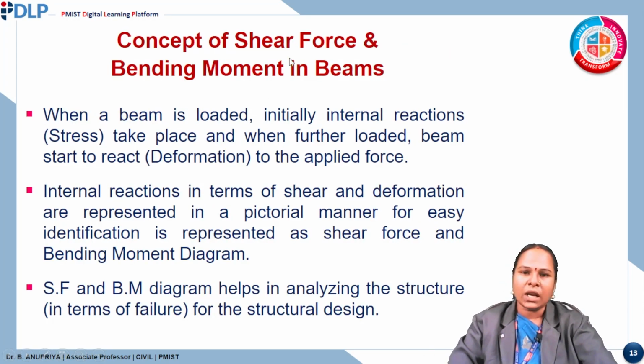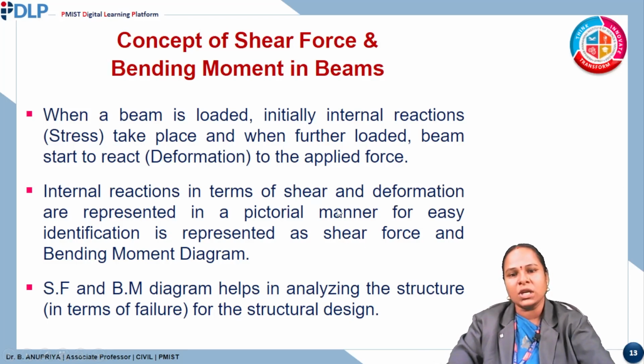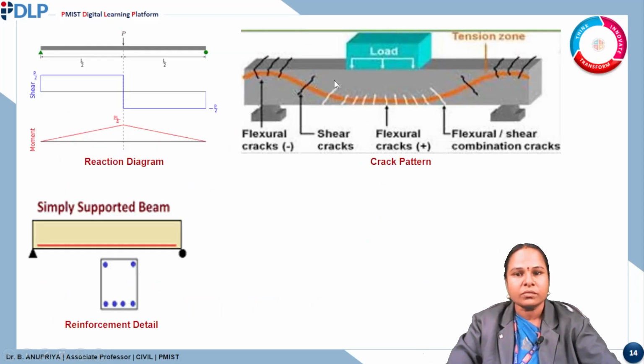And why do we want to calculate the shear force and bending moment in a beam? When a beam is loaded, some internal reactions take place due to stress and strain. It leads to shear and deformation. The shear and deformation are represented in a pictorial manner for easy identification, called the shear force and bending moment diagrams. So, shear force and bending moment are helpful to analyze the structure for structural design. This is the main concept for which shear force and bending moment are calculated.